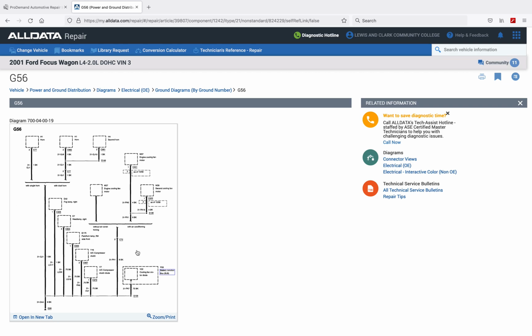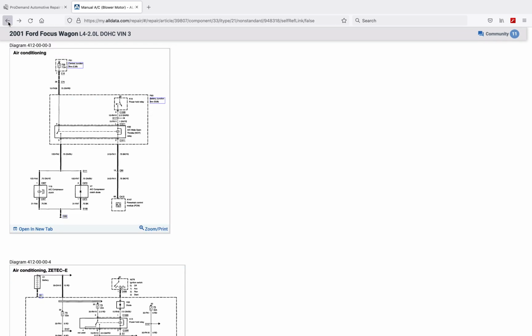The reason that's nice to know and really need to know when we're dealing with service information is if we have a car that comes in and the customer's complaint is my horn doesn't work, my right fog lamp doesn't work, my cooling fan motor doesn't work, and maybe my AC compressor doesn't work, those are noticeable symptoms that the customer throws at you. Having access to a wiring diagram may show you that G56 is a common point where there could be a failure that shows up in a diagram. So again, that's how it's going to help us specifically in appropriate context.